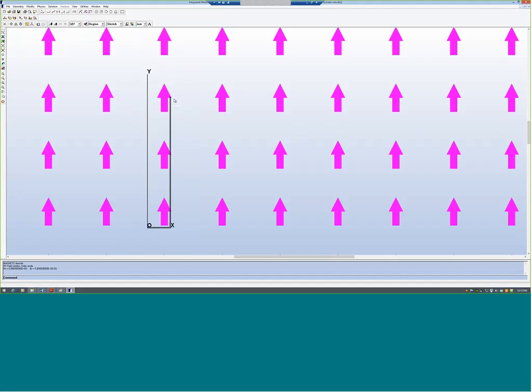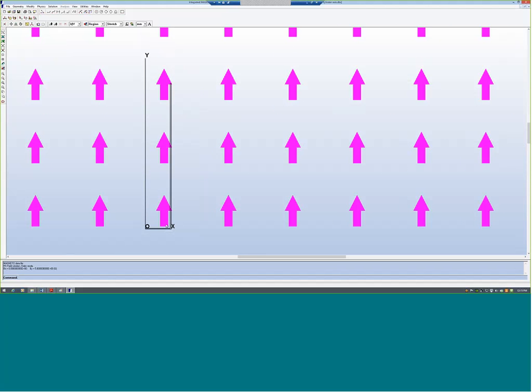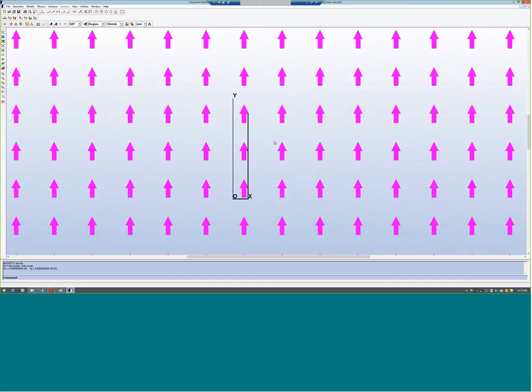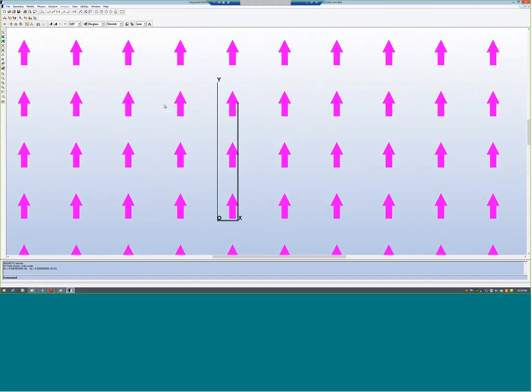Once I have a cylindrical can, what is the field inside? And I'm using a 10 mm, the same 1 centimeter thickness. Then what is the field inside? That is the problem. Now it is the reverse. Now you've got fields here, 5 Gauss, or whatever field, 1 Tesla or whatever, and now the inside field is a smaller field. For this kind of problem, the finite element method is best suited, compared to the boundary element method, because it is an inverse problem compared to the previous problem we solved.